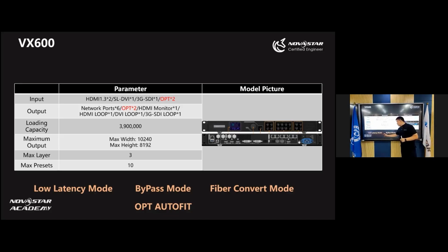For example, it supports the bypass mode. What is a bypass mode? It's very important because for the independent controllers, it has latencies of like one frame. But if we use all-in-one controllers, normally we have 2 more frames, like three frames. If we use the bypass mode, it will just disable the video processing part. So it can also work like the independent controllers if we just enable the bypass mode. And also we can enable the low latency on this mode.